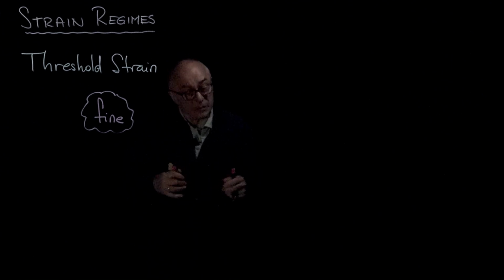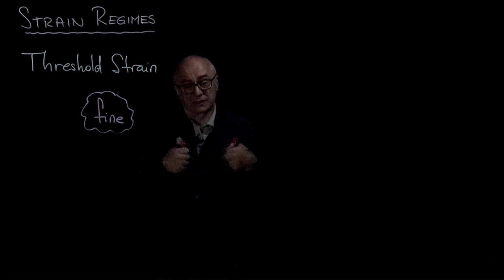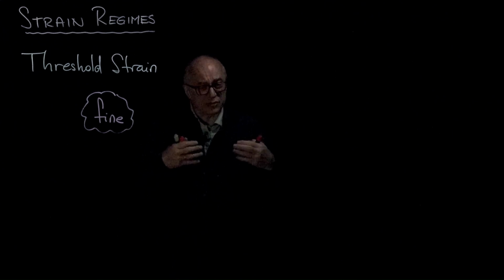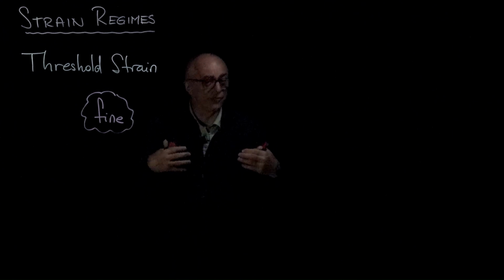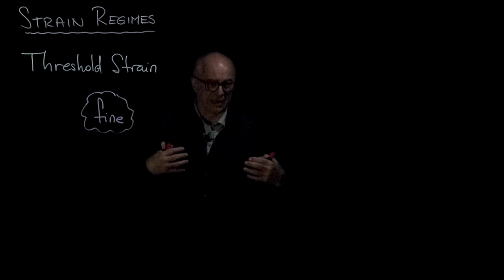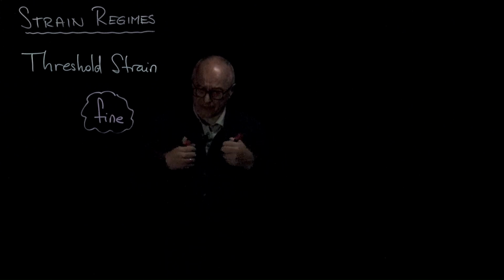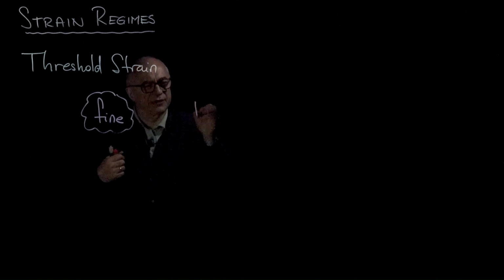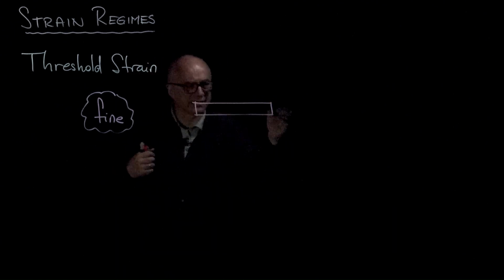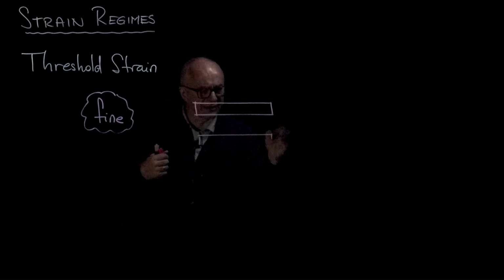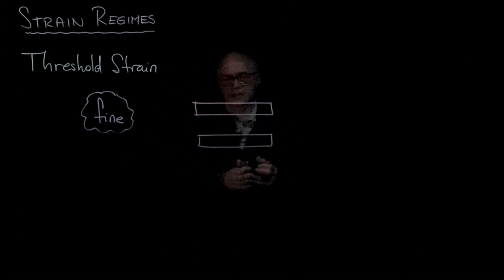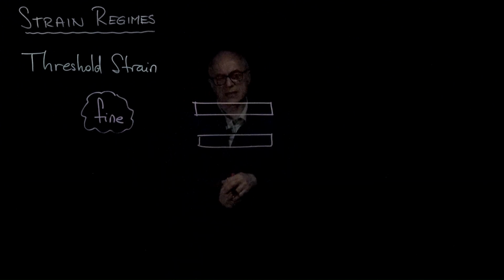And so now we cannot think of solid-to-solid contact and a Hertzian contact. Particles actually feel each other before they touch each other, and they interact through electrical forces. And so now we have to think in a different way. So let's say that this is a particle, and it's interacting with these other particles through their double layers and the osmotic pressure, double layer repulsion, van der Waals attraction.